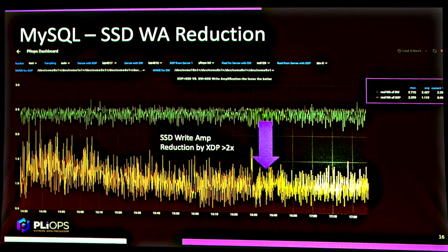Because SSD flash works on program erase cycles, the more you write, the faster it will retire. So if you expect 3 years, the faster data ingestion and write amplification will reduce the lifespan from 3 years to a year and a half or even 1 year.